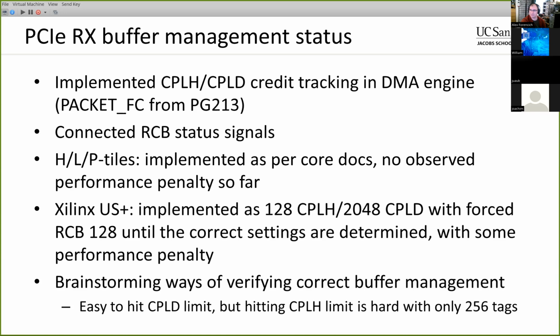is there some other tool that can be used to verify that? I was thinking simulation could be an option, and I actually tried running the test bench for the Xilinx PCI Express hard IP core, but I'm just going to say that test bench leaves a few things to be desired. I think their testing only does single DWORD reads, so it doesn't look like the infrastructure is there in their root complex BFM to actually generate multiple completions for a single read request. That's problem number one. Problem number two, it's terribly, terribly slow. Yeah, so I'm not sure what makes the most sense there.